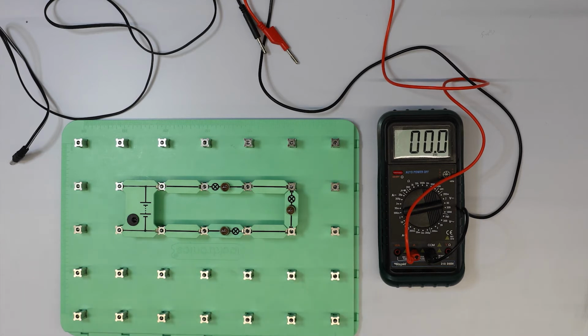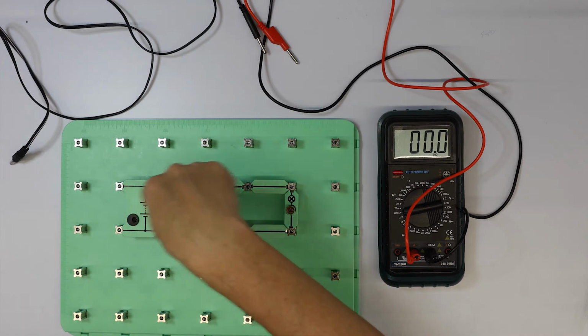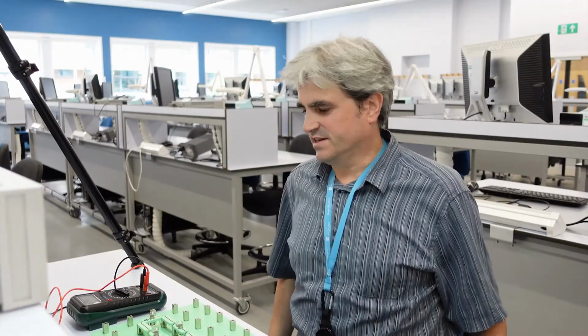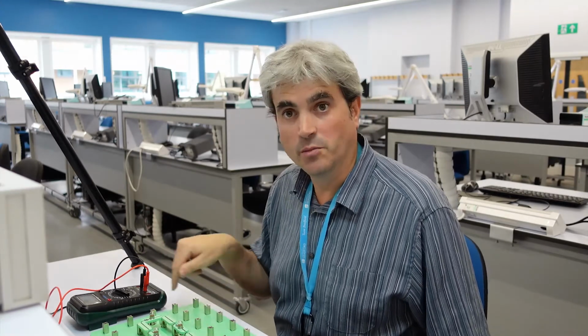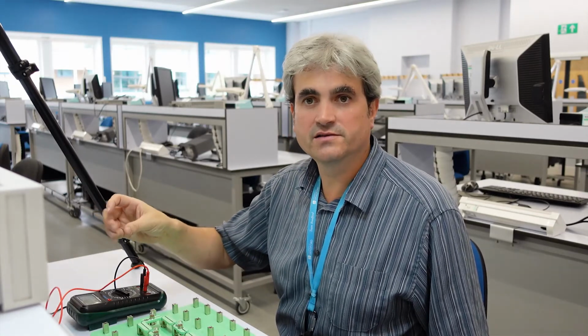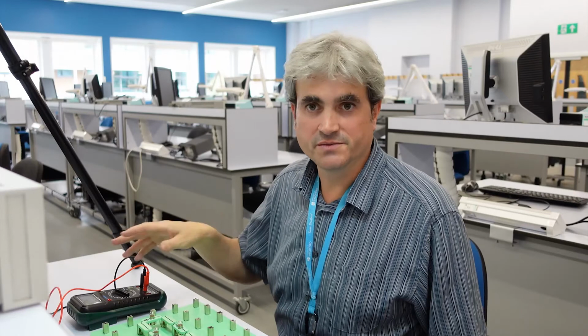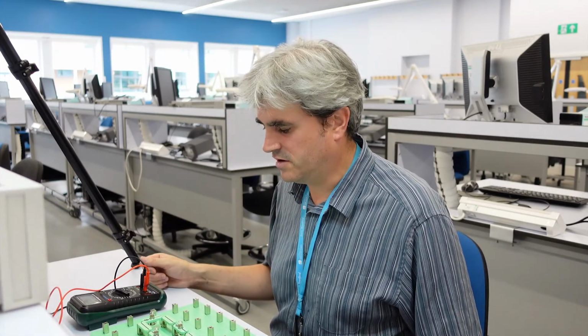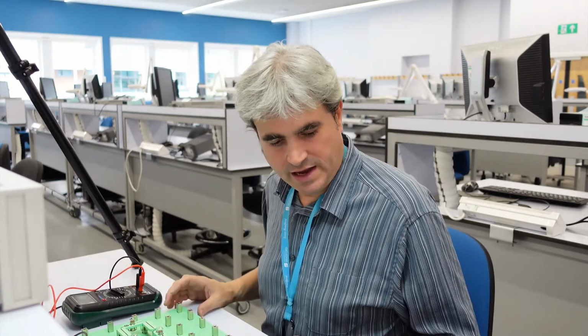So now I'm going to set up what's called a parallel circuit. So here, all the bulbs are in series, so there's one wire that connects all the bulbs going around the circuit like this. And this is actually a very common way of connecting bulbs. If you imagine the bulbs on things like Christmas tree lights or celebration lights, they're normally connected in series, so one bulb after another. The problem is if one bulb blows or fails, then that takes out the whole string of bulbs. So sometimes it can be quite difficult to find out which one has gone. In modern lights, sometimes they're more likely to be connected in parallel to avoid that problem, so you can lose a bulb and not have that issue. But now let's set up our circuit as it's shown in part B.